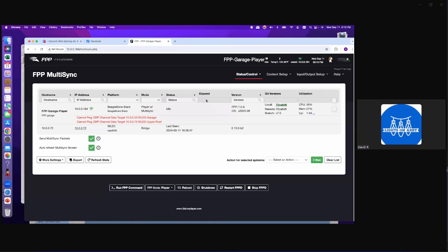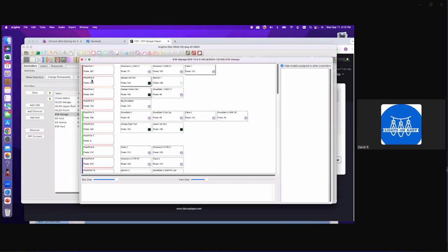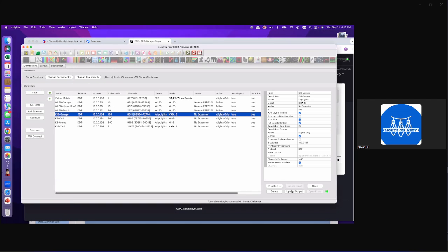It just sends and floods every channel that's available with pixel data. So if you're testing from your controller, hit the test button, you will see everything that works. But if you're testing from xLights and you're only getting 25, and you know you've got it configured to 388, then maybe you haven't uploaded that configuration, and you would upload the output to your controller, and then it would have the settings. I've already uploaded this one, so I'm not going to go through it again. But you would upload the outputs, and that's how you get your pixel counts, your channel numbers, and all that